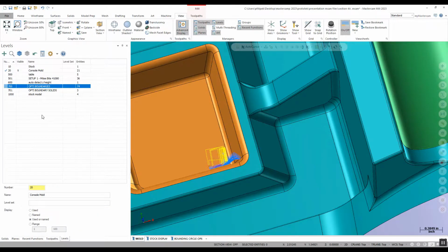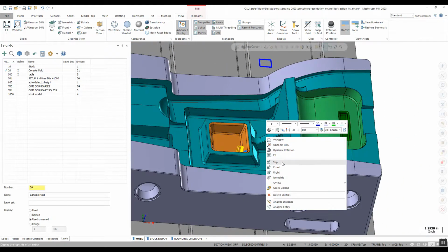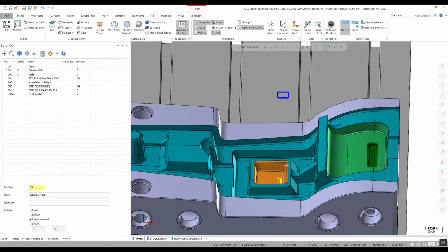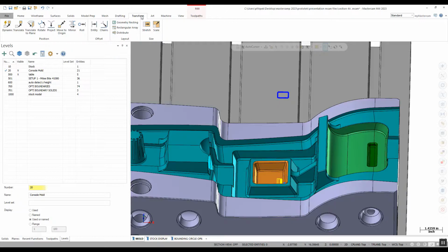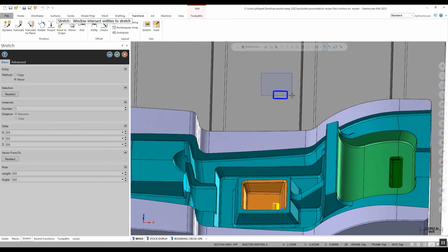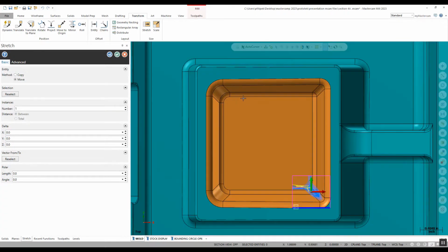Now, the only other thing I really need to show you here is my boundary. So how I just got that to cut there is I had a normal containment boundary. Now one thing I did pick up here that I thought is really useful is what if I want to extend that or move that bounding box out, which I do quite a few times. Instead of remaking it or retrimming the lines, you can go to stretch, and the trick here is just to pick 3 entities. So instead of picking it all, you'll always leave the one you want to stretch from back in the selection.